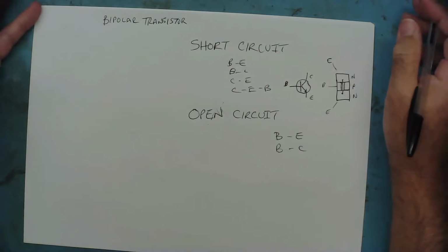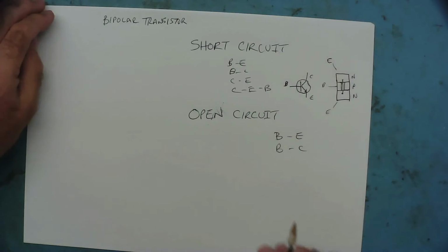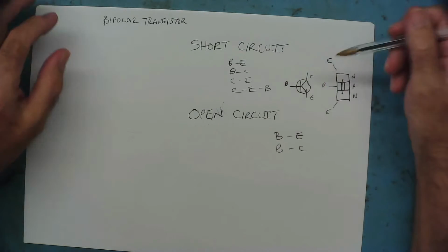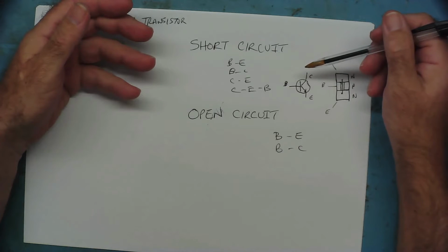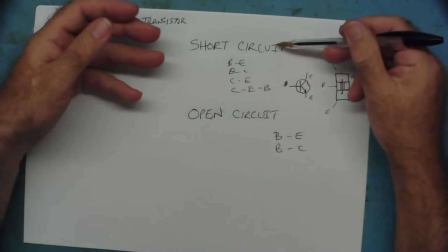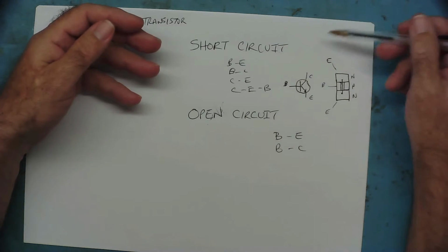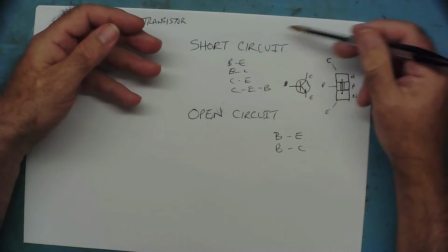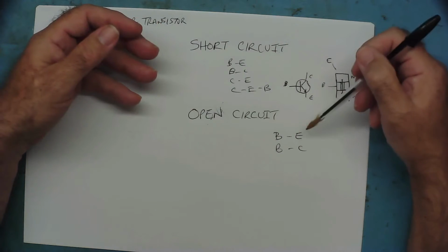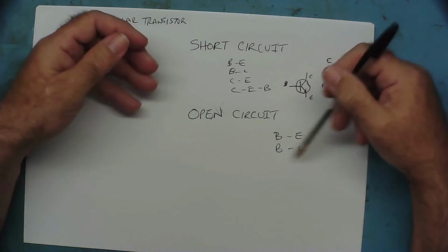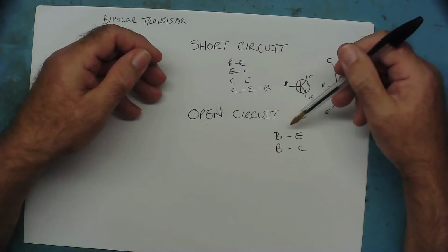That's two things that can go wrong with transistors. The reason for these sort of failures would generally be because of some abnormal circuit condition. So for instance, a transistor is driving a load, and the load has become short circuit, and therefore the transistor passes too much current and it blows, it goes short. Same with open circuit, generally tends to occur with incorrect voltages.